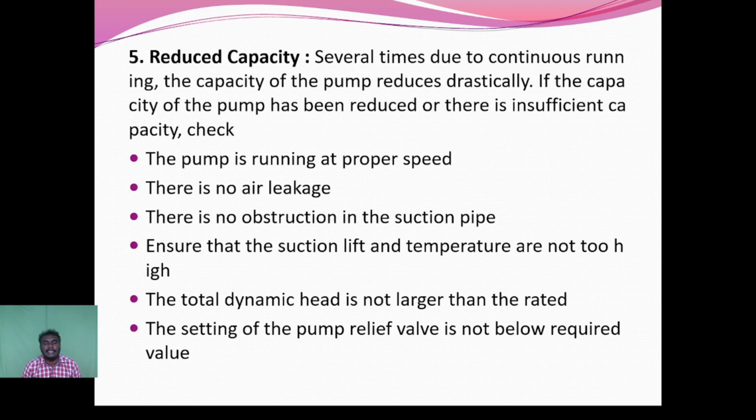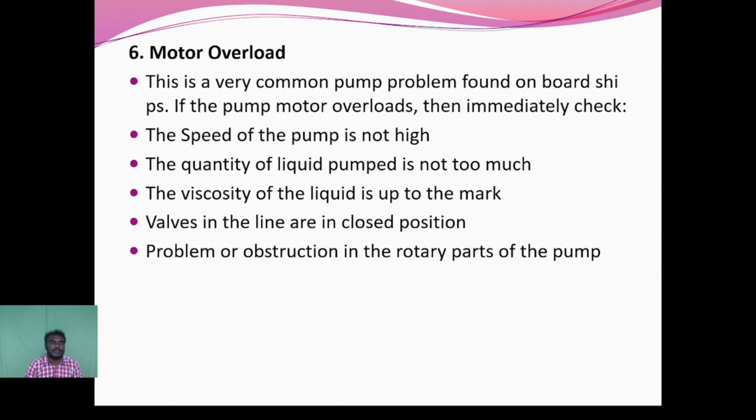Ensure that the suction lift and the temperature are not at a high level. The total dynamic head is not larger than required. Then the setting of the pump relief valve is not below the required level.